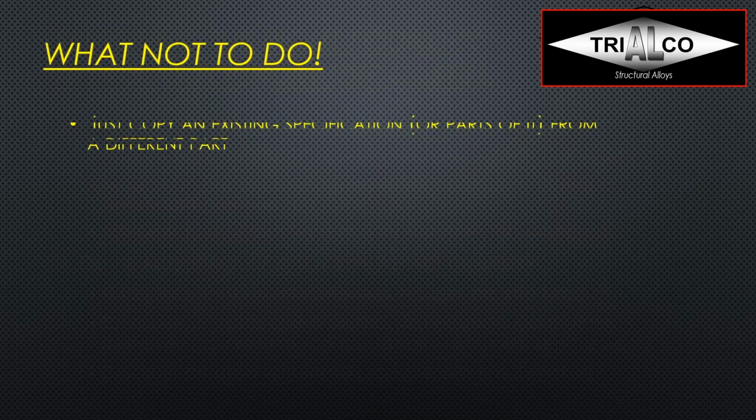So with that now, I would like to point out a few things I do not want you to do. Let's start with copying an existing specification or parts of it from a completely different part. Just because you say, it's kind of similar to this one, I just copy it without even looking through it. So very often in this case, you will find things on the drawing or in the metal spec that just made the ingot a lot more expensive for no reason at all.